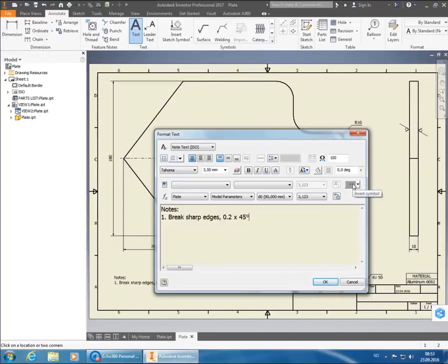The reason we add this one is that once this plate has been cut, it's going to have fairly sharp edges, which you can actually cut your hands on. And by adding this one, we're telling them to either use a light grinder to grind the edges slightly, or just to use some rough sandpaper and just sand the edges so that they sort of blunt the sharpness of it.